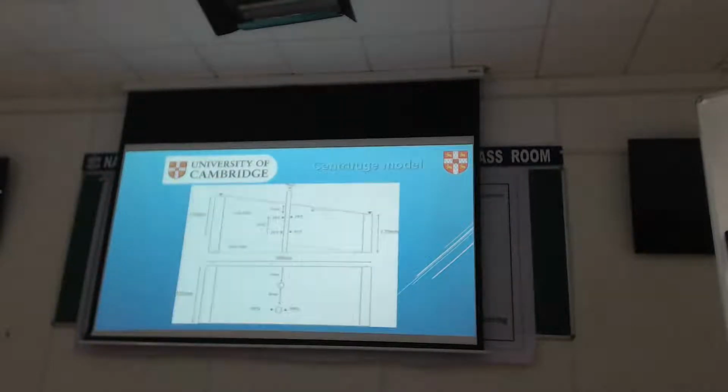One other feature I forgot to mention is that I felt it was important that we model the seepage in the slope. So we were maintaining the water level at the ends of the box at a given level. We had peristaltic pumps pumping fluid back up in front so that the flow could continue, and we got a steady seepage parallel to the slope, which is a condition not often done in many other experiments.